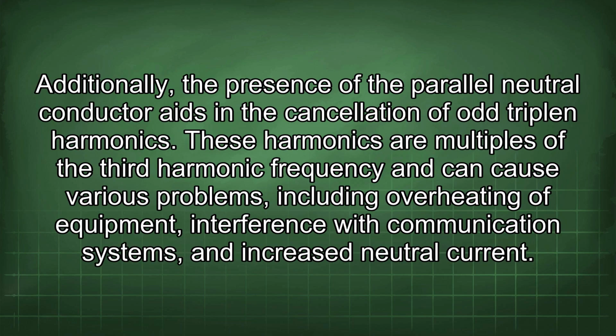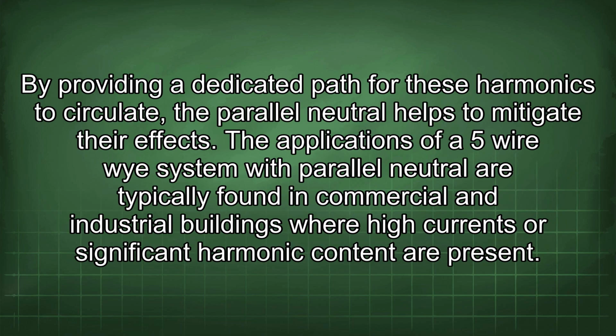Additionally, the presence of the parallel neutral conductor aids in the cancellation of odd triplen harmonics. These harmonics are multiples of the third harmonic frequency and can cause various problems, including overheating of equipment, interference with communication systems, and increased neutral current. By providing a dedicated path for these harmonics to circulate, the parallel neutral helps to mitigate their effect.